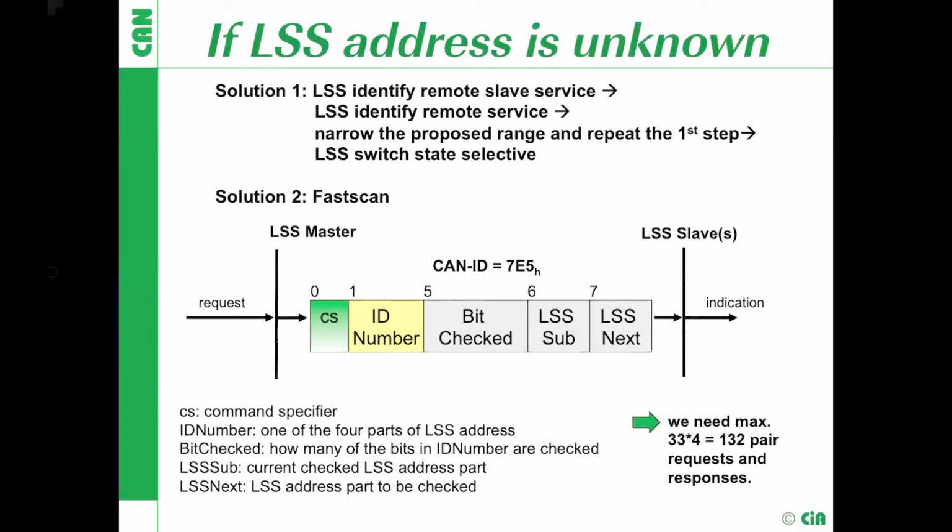After several scan cycles, the LSS master can have a single LSS address. This solution uses long and limited scan cycles, and the back-to-back messages are also a drawback for CANopen devices with limited performance. So it is not recommended to use this solution, and I will not introduce it in detail.